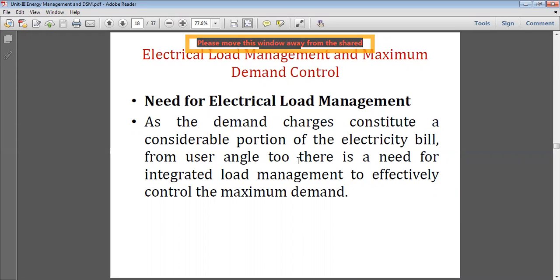one by one. But we have studied what is the advantage of power factor management. It has two advantages, categorized as technical advantage and financial advantage. The technical advantage is that the current in the distribution line will be small, so the rating of switchgears can be reduced. It will reduce the heating effect, failure of the terminals, and maintenance. These are the technical advantages.